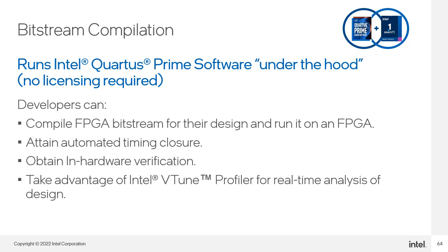The eventual clock frequency will be reported back, showing you what the achieved clock rate for the FPGA was. Also, there is no need to perform verification from a simulation standpoint, since pre-tested IPs are what is put together for the FPGA. However, you may want to ensure that you are getting the exact results achieved at emulation. If you have used some pragmas or attributes that you asked the emulator to ignore, you will need to enable them at this stage of the development, and this can potentially affect your results.